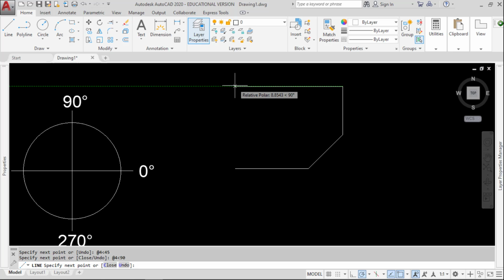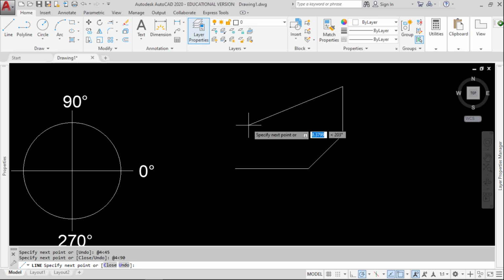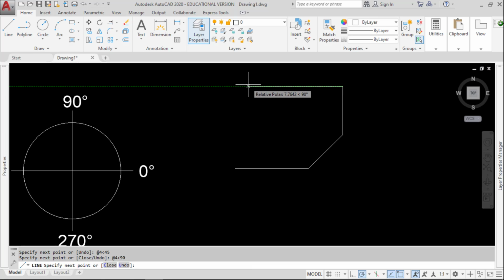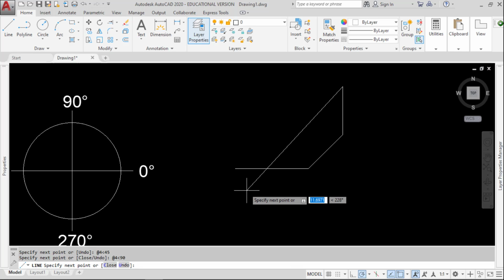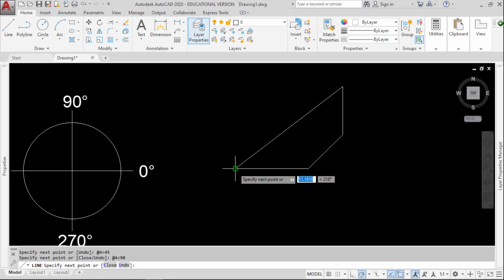One trick, if I want this line that I'm currently drawing to line up with the left end of this line here, my first line, I can hover this point. Now this is important. I'm not selecting anything. I'm putting my cursor over the left end of that line and I'm letting it sit there. I call it hovering.